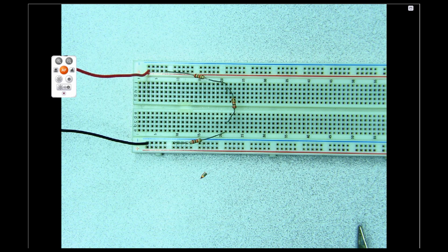So that's how you can measure current in a circuit. And that will always work, no matter what kind of circuit you have, whether it's a series circuit or a parallel circuit. If you want to measure current through a resistor, you just pull out one leg of that resistor, pop in a wire where that resistor used to be connected, and then hook those two loose ends of the circuit up to your meter, okay? All right, so that's how we can measure current.